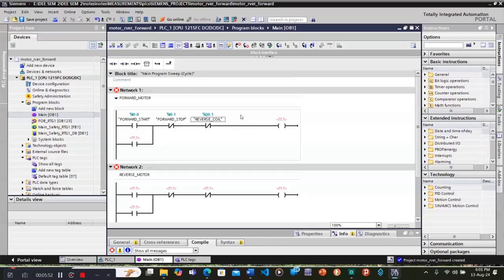So that's why we bring a latching mechanism so that we store the address of the reverse coil here so that when a power is moving, once it is here and we have energized the forward direction, then this one is always in the low state. So it will always move, but then in the reverse direction, this motor is not going to be, the coil is not going to run.